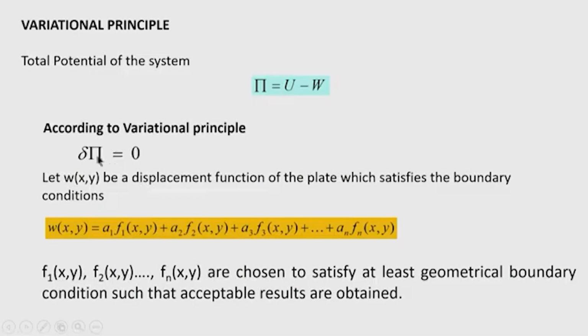It also has to be borne in mind that if you choose a very complicated function, even if it satisfies the boundary condition completely, the computational effort, that means the integration that is required in the variational principle, finally will be very lengthy. So, some authors, say Blasov, have mentioned the eigenfunctions of the beam to form the approximate deflected surface of the plate for different boundary conditions.